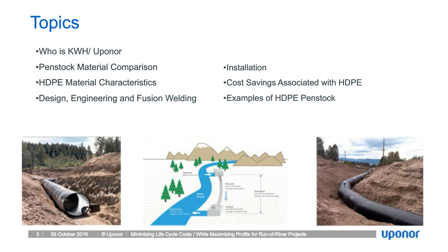For run-of-river projects, we define as low-pressure, high volume. High-density polymer-based solutions, or penstock materials, are growing more in demand due to their economic benefits and structural offerings. So the intent is to kind of offer up the information between conventional and the new emerging technologies, to help you, the engineer and end user, in understanding the possible benefits when considering structural high-density polyethylene as a penstock material.